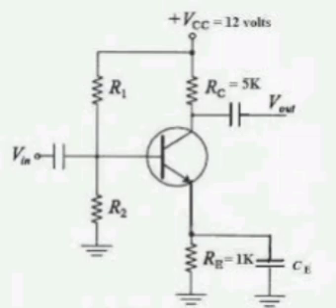It is clear from the above analysis that the battery EMF E, the meter full scale current IFS and meter resistance Rm determine the resistance R1. The resistance R1 and the meter resistance Rm determine half scale resistance RH. Thus the meter resistance scale depends only on the meter and the voltage of the battery.